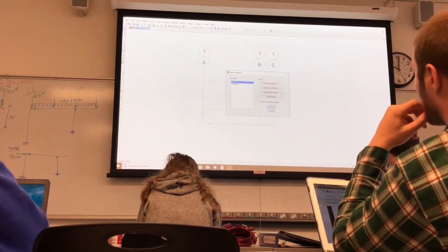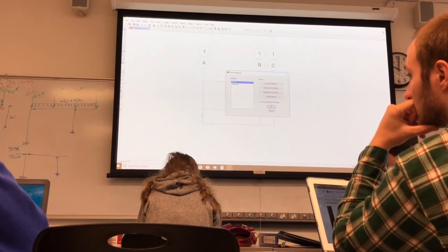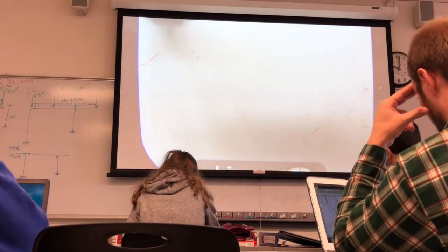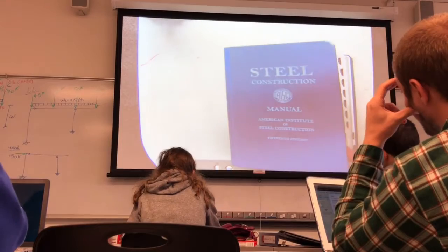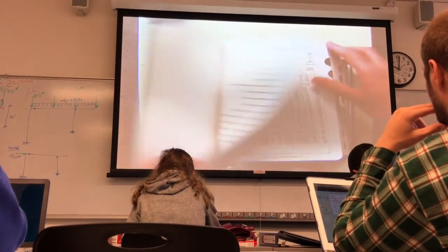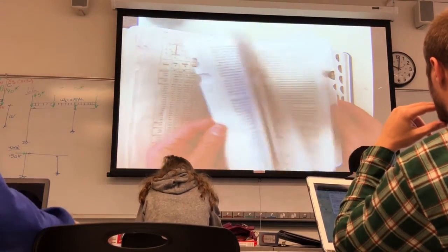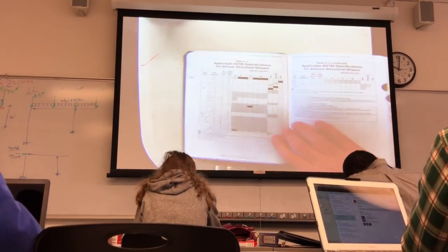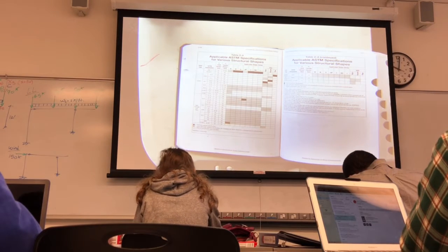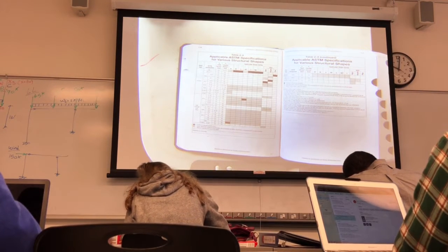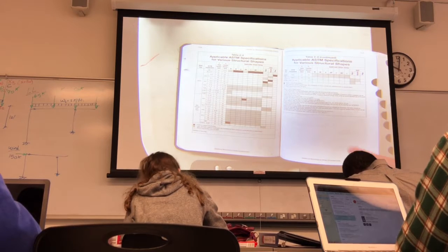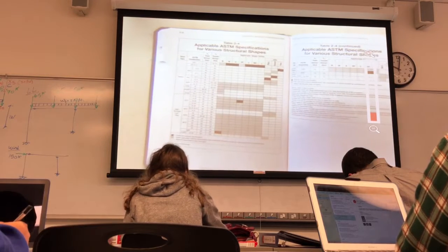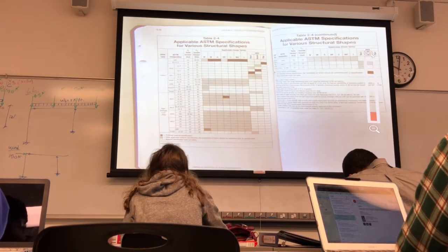First of all, I'm using a W section, right? So when I'm using a W section, I need to know what type of steel I'm using. So I go to table 2-4. If I don't give you the material type, then you're gonna select the preferred material from table 2. We talked about table 2-4 before, right? We're using a W section. So which material should I use then?